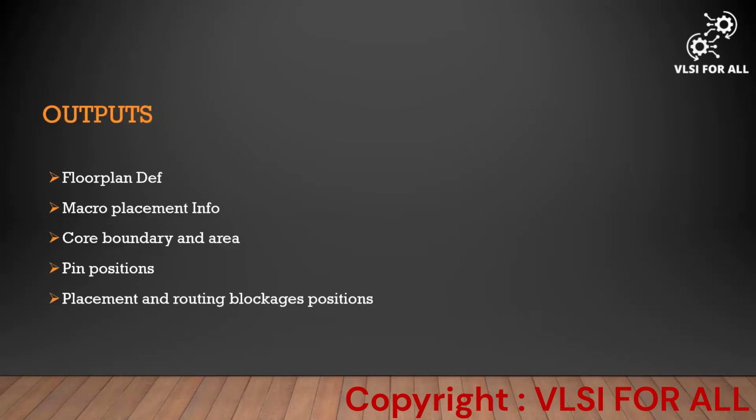Moving to the next stage, outputs. Once we finish all the floor plan, we will dump the outputs. The outputs we will dump are the floor plan DEF, with the macro placement and information. Core boundary and area, pin positions, placement and routing blockage positions will be present. So all these outputs have to be dumped once the floor plan is complete.